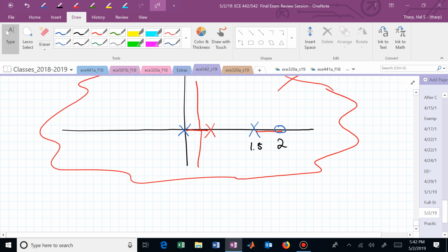How many branches do I have? 3. How many are terminating at finite zeros? 1. Oh, I have 2 branches going off to infinity. That means I'm at plus and minus 90 degrees eventually. And you could find the sigma and the asymptotes for that if you wanted to. That's probably not necessary, because now you say, oops, that's not what I want, and just exit off.